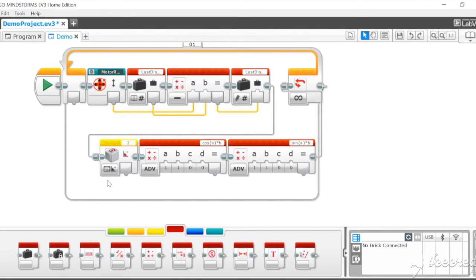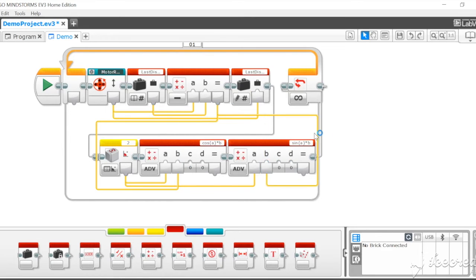And so now you just plug in the gyro read into port A of both of the blocks. And then take the... oh, hold on, sorry, that was an issue. So here, instead of putting subtract into last distance, you have to put the motor read into last distance. And then you put the subtract maths block into port B of both of these blocks. Sorry about that. So now what this will do is it will calculate the changes in X and Y since the last measurement.